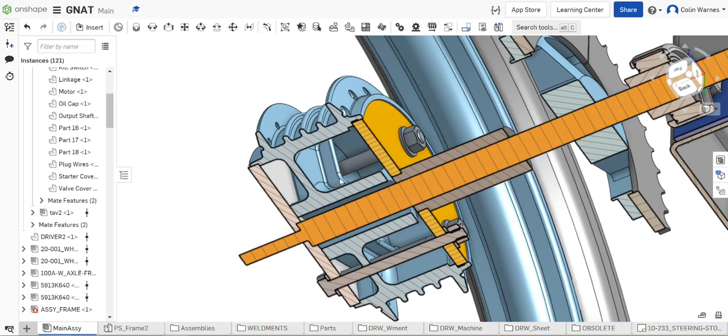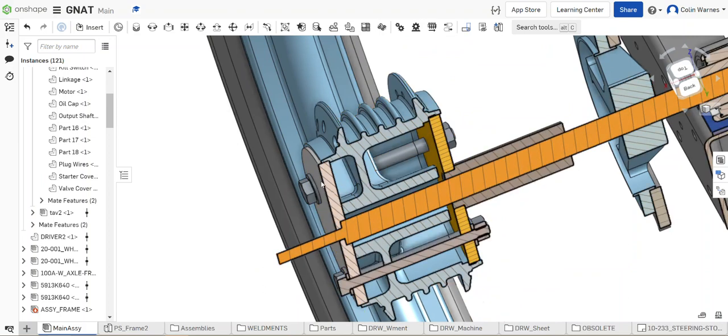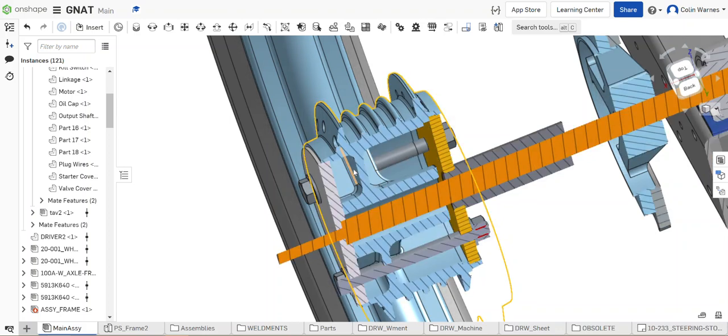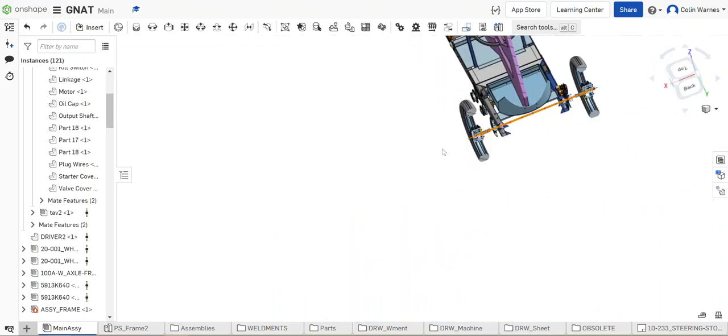And then I've got these plates I designed such that they pick up the mounting holes, or the 4 holes that I drilled originally in the CT90 hub. Picks those up, so you don't have to drill a different set of holes in the hub. And then the thing I like is my axle goes all the way through the hub assembly. So I'm supporting my hub completely on the axle. I'm not cantilevering it out with a single mount like most cycle carts use.